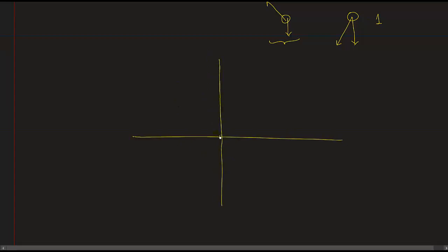So this is my neutral axis and this is my bolt number 3 and this is the distance. In this case, this force is coming due to pure moment and this force is coming due to pure shear, and that is nothing but what we have already calculated. This value is P by 6. Let's call this angle theta.